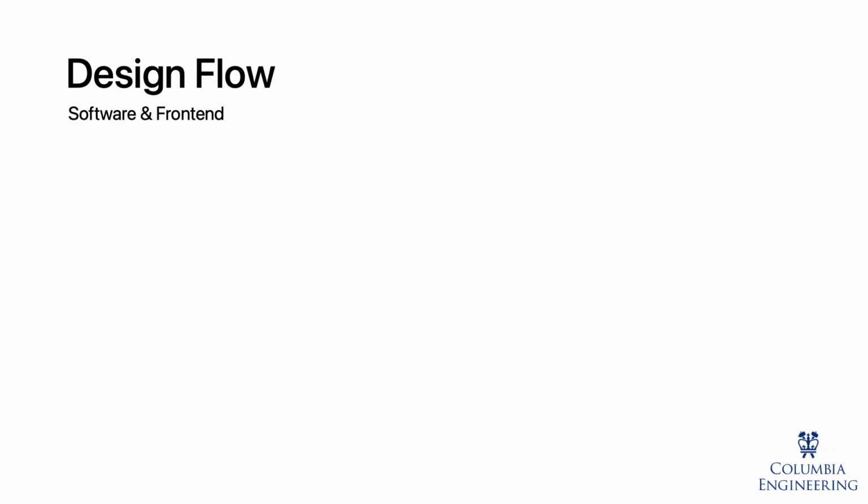Now let's talk a bit about our design flow. The project began with designing the reference model, which is a standalone C++ application that implements the algorithms and renders the objects. This model helped us to understand the required computational complexity that we needed to support in hardware and also served as the golden reference during verifications.